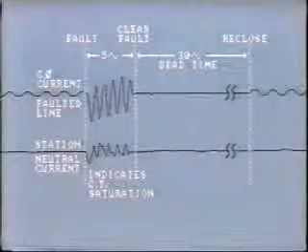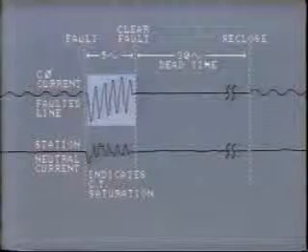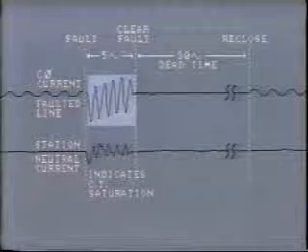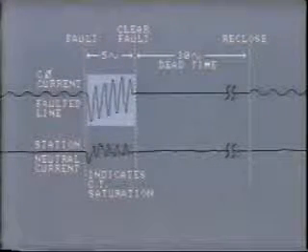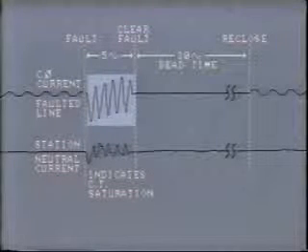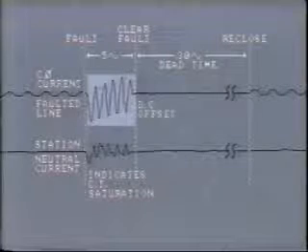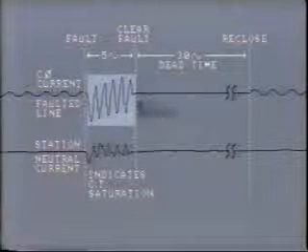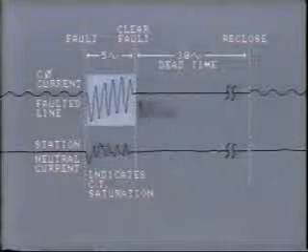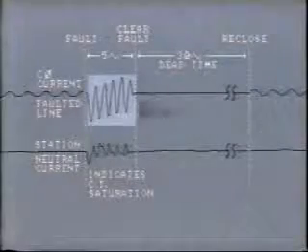In this case, the saturation is caused by the fact that the fault current is not symmetrical. There is much more negative magnitude than positive. This offset in the fault current is called DC offset, and it has the same effect as adding burden to a CT. The CT secondary output becomes distorted and no longer accurately reflects conditions on the system.